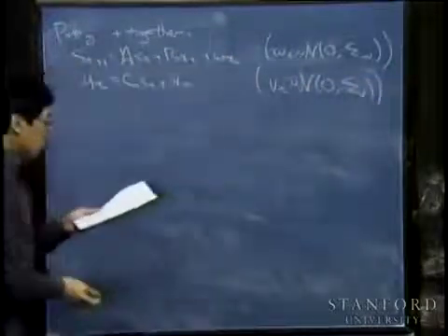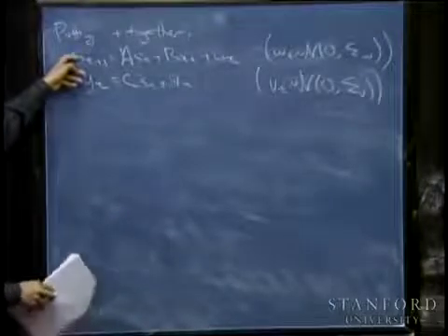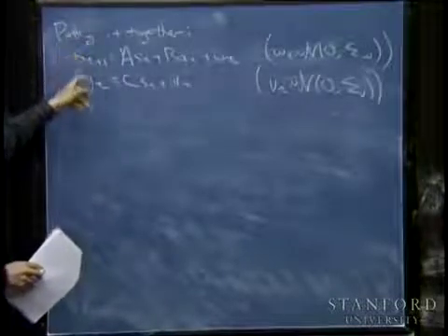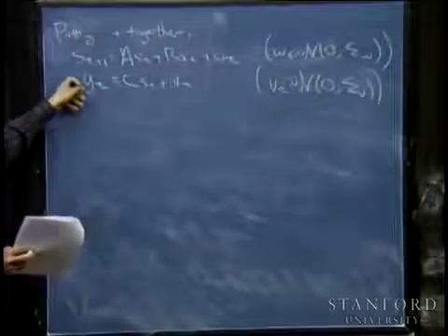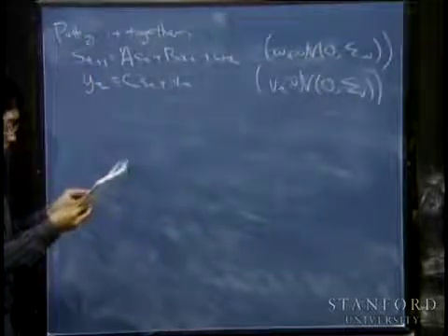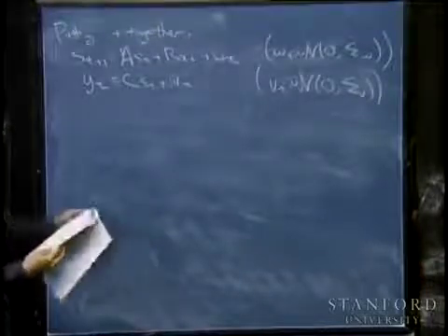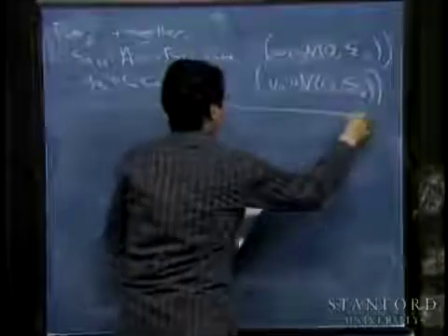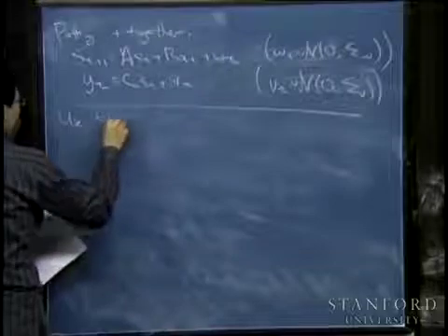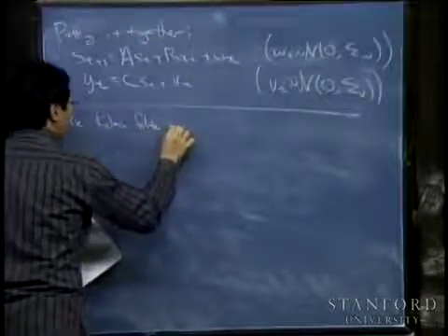Okay. So in an LQG problem, or linear quadratic Gaussian problem, I have a linear dynamical system that I want to control. And I don't get to observe the states directly. I only get to observe these variables yt. So I only get noisy observations of the actual state. It turns out that you can solve an LQG control problem as follows. At every time step, we'll use a Kalman filter to estimate the state.